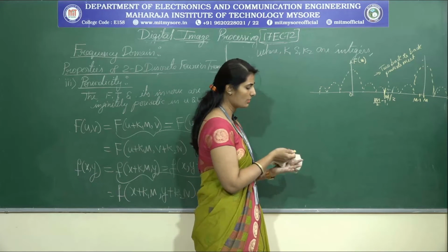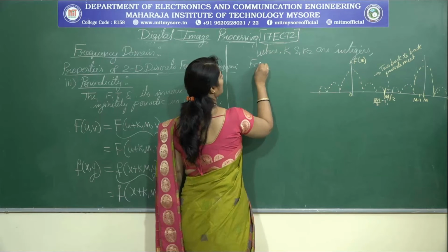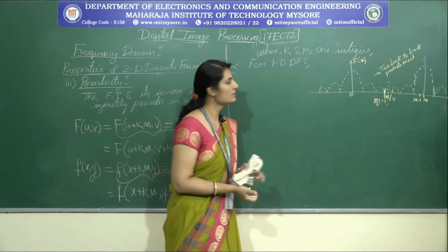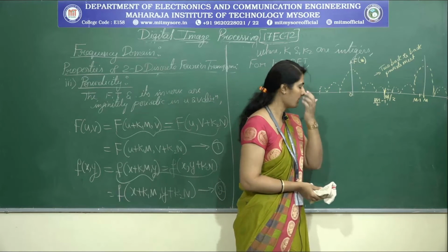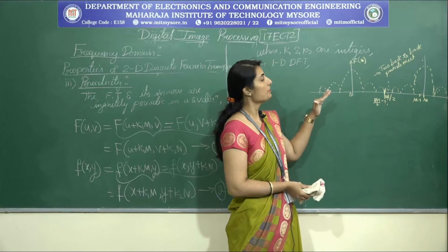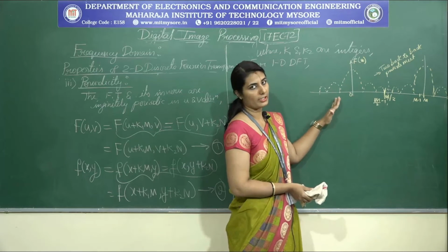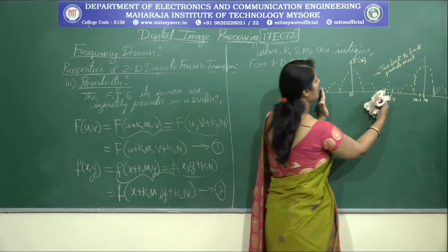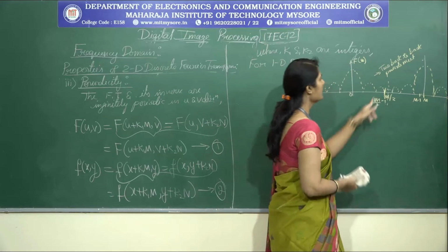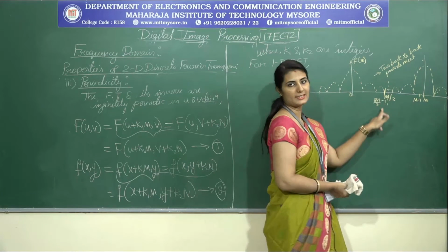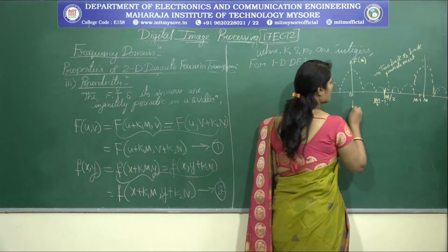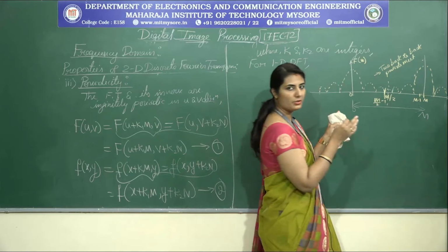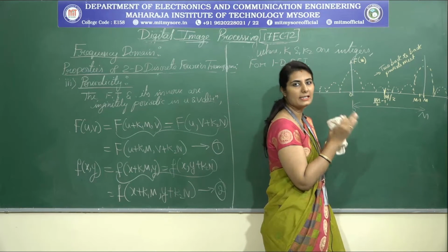This one-dimensional signal is infinitely periodic. Here I have considered two periods: this is one period, this is the second period, and this is the point where two back-to-back periods meet. The sample duration is 0 to M, but in this duration we do not have one complete single period.